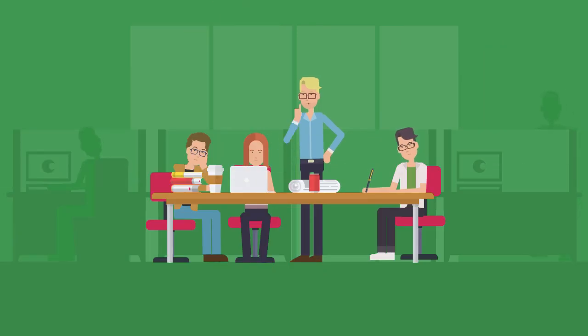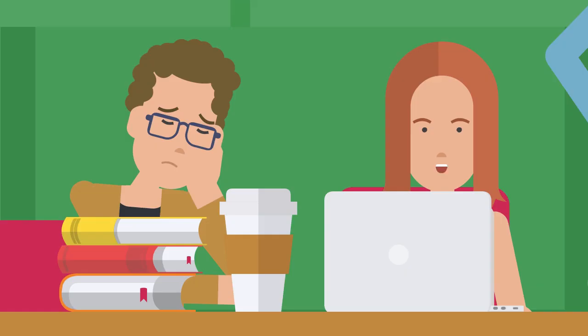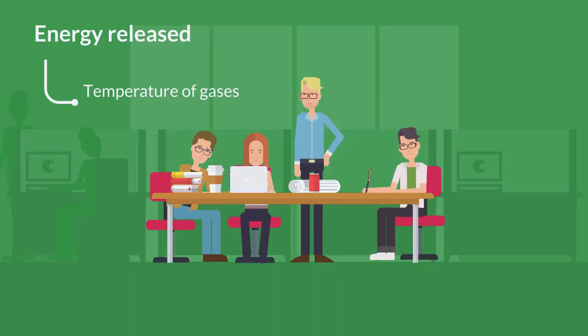Then, Professor, when calculating the energy released in a boiler, I only need to know the lower heating value. No, Jane, you need to know the temperature of gases at the chimney. The hotter the gases, the lower the energy you get. And that's all? Not really. You must also consider other losses like those through the boiler walls to have a final calculation of the energy efficiency.